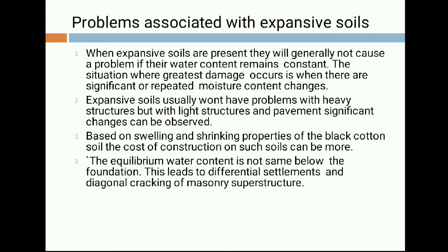Expansive soil usually won't have problems with heavy structures, but with light structures and pavement significant changes can be observed. Means in case of light structures and pavement kind of structures, they are more susceptible to experience the shrinkage and swelling property of black cotton soil. Based on swelling and shrinking properties of black cotton soil, the cost of construction on such soils can be more. Means the amount of money that needs to be spent on the treatment of black cotton soil can affect the overall cost of the construction.